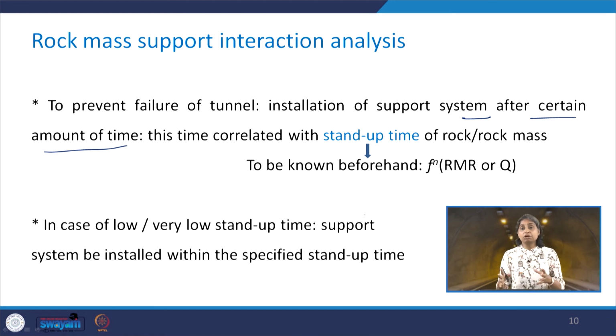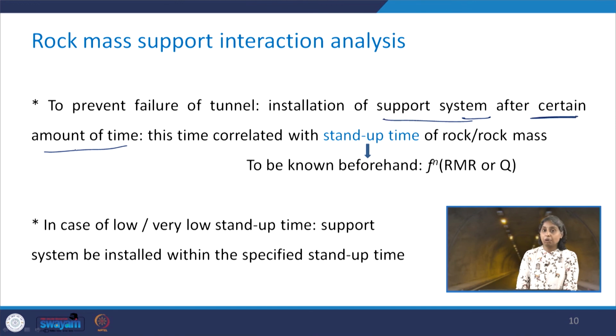Now, why should we install the system after a certain amount of time? Because if we apply the system immediately, there is going to be a lot of support pressure onto the support system and we need to go for an extremely rigid support system, and that may not be economical. So, we provide the support system after a certain amount of time. What should this time be? This time is correlated with the stand up time of rock or rock mass and it should be known beforehand.